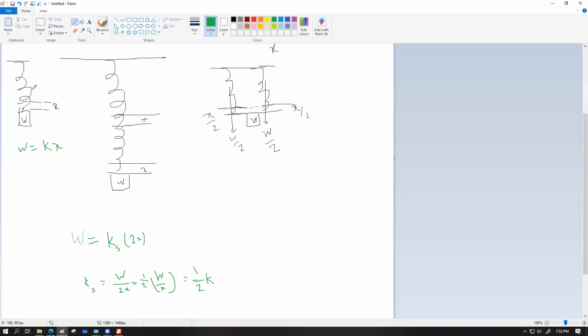So bottom line, if we attach multiple springs in series, or add multiple layers within a series combination, here I'm saying this one has one layer, this one has another layer. Why I'm using the word layer is going to come after a little while. So if we attach multiple springs in series combination, the total extension of the setup becomes bigger than a single spring, and that makes the spring combination softer compared to a single spring. That goes for the series combination.